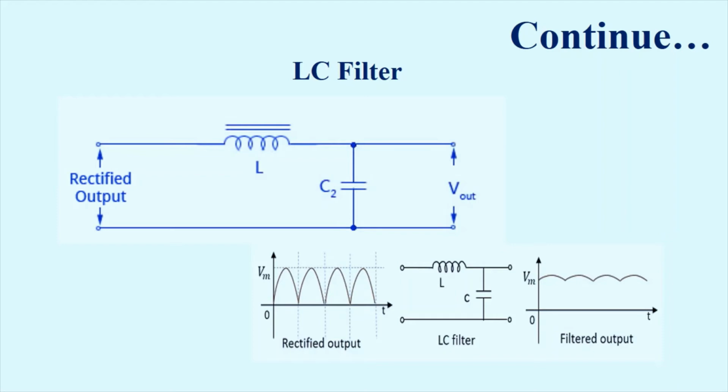In this DC, we also have some portion of AC component. After that, when this reaches the capacitor, the capacitor passes the AC signal to the ground and we have only DC at the output of the load resistance. So ripples will be decreased at the output and we will get nearly pure DC.